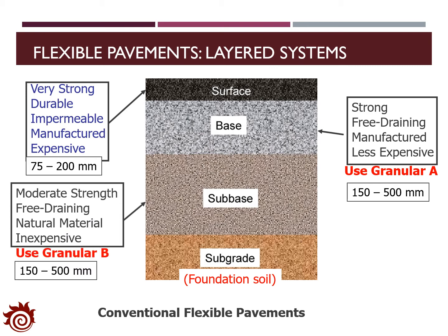Below is the subbase layer. It has a moderate strength and is free draining. It will use natural materials to construct the subbase layer, so it's not expensive. Usually we apply the Granular B material. The depth of subbase varies from 150 to 500 millimeters.